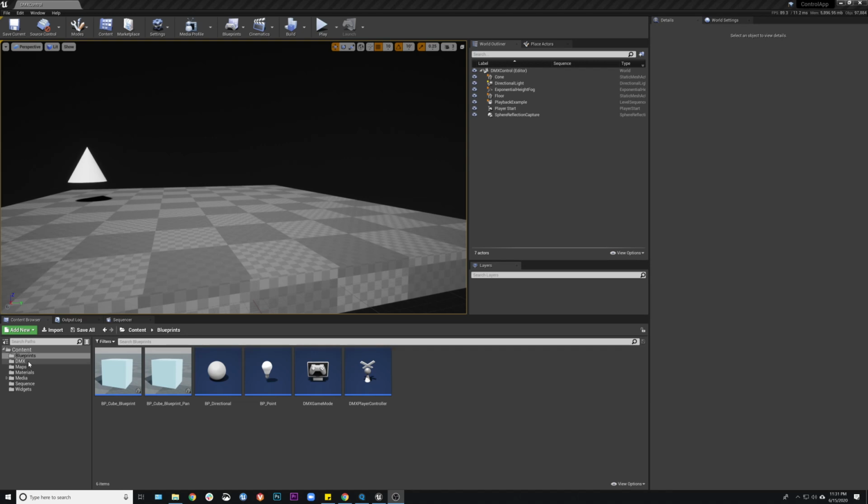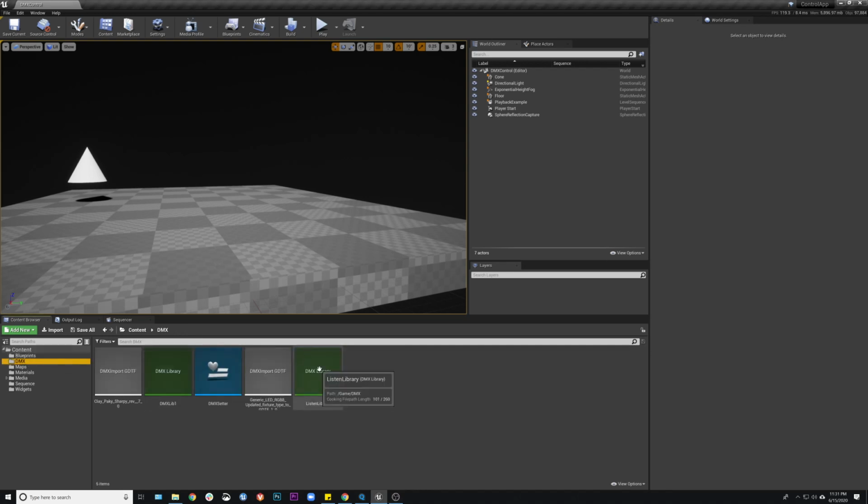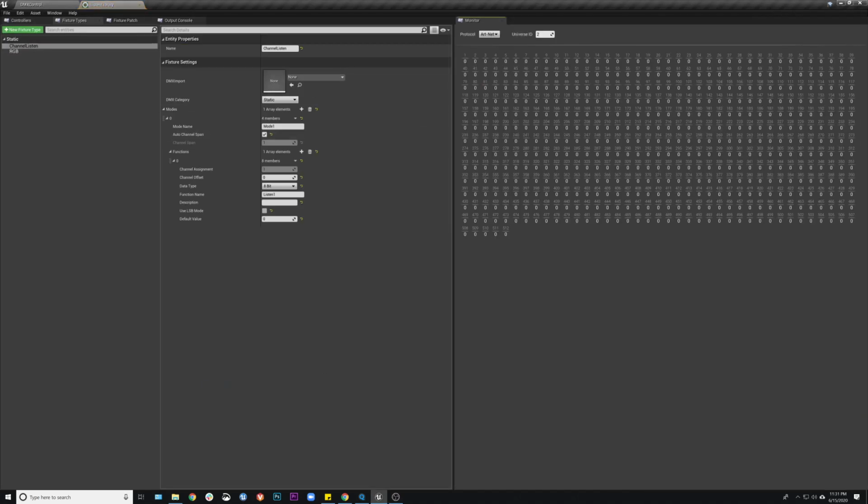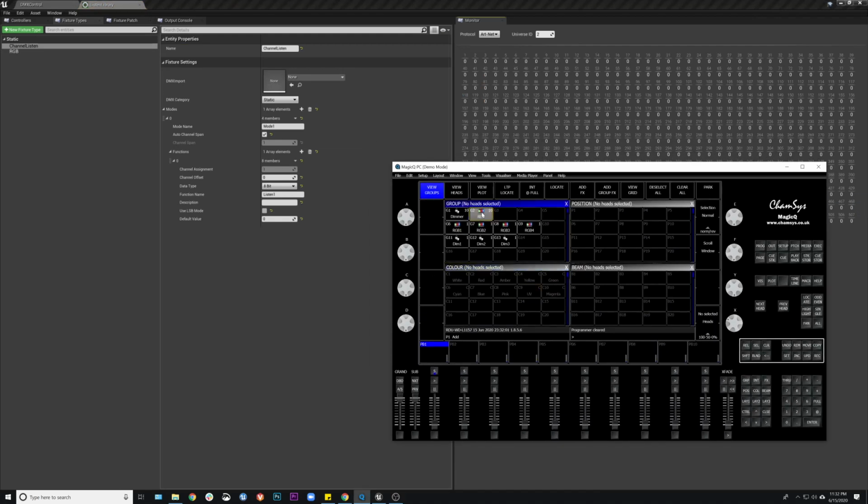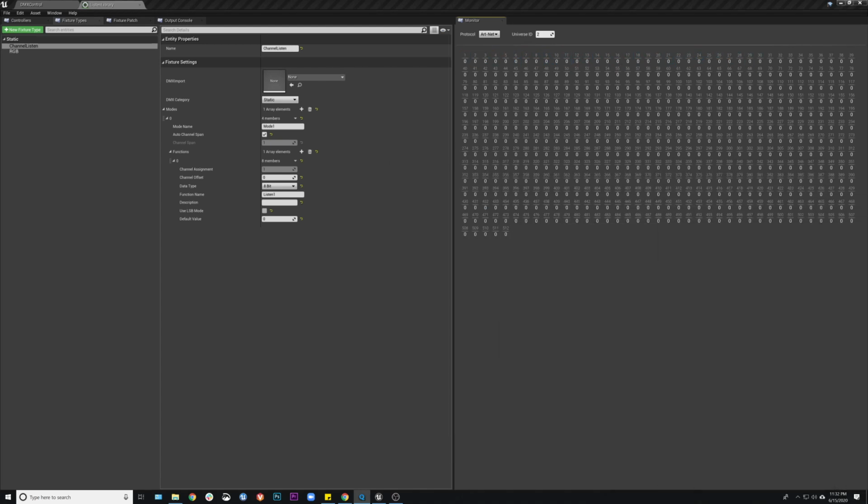Again, I'm going to do this live stream style, so if there's errors, I'll just try and keep going, and I apologize in advance. So I've already got my DMX proven here. I'm running a little CamSys session over here. So if I turn some things on, you can see input. So that's number one. Make sure you're getting DMX input before you even start, or this will probably be harder to troubleshoot.